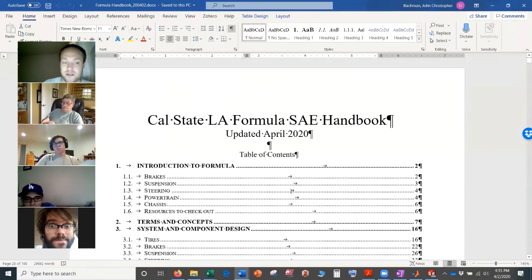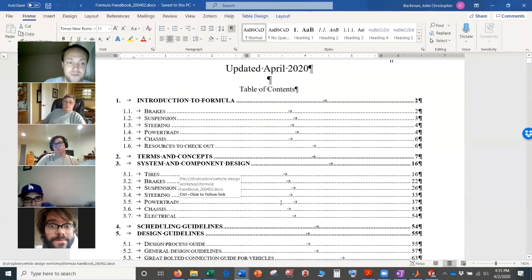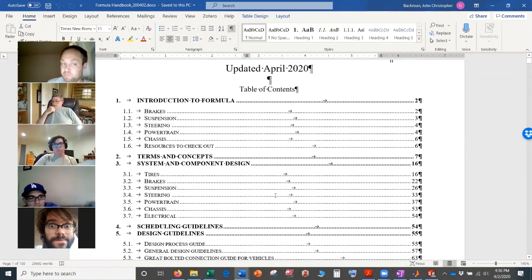What about camber change with steering and caster? Camber change with steering. Oh, yeah, I would probably avoid it. I mean, you want your tire to remain upright at all times, so I don't know if you'd want to camber your tire. Well, it's camber change with steering, and how that affects things with caster for the front steering. So you go in the corner and you have camber change, and then you're also turning your wheel, and how that helps or benefits you.